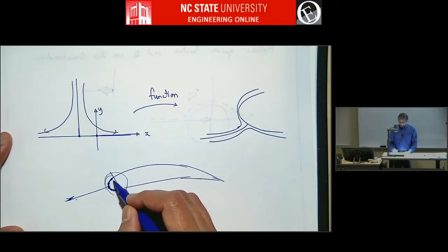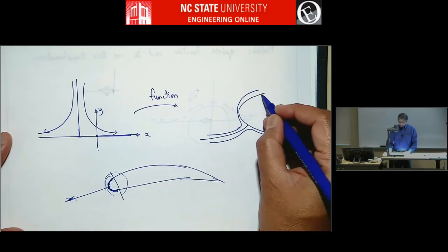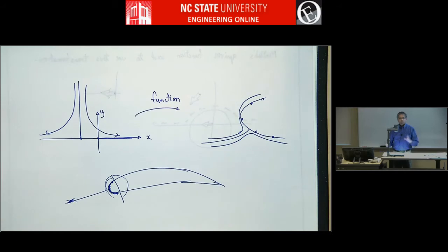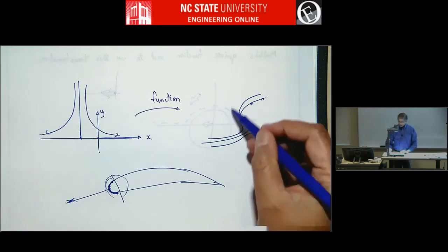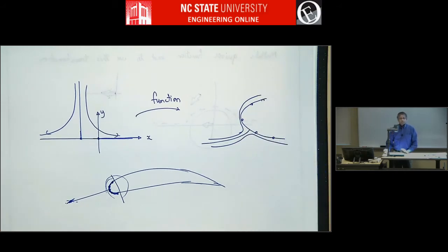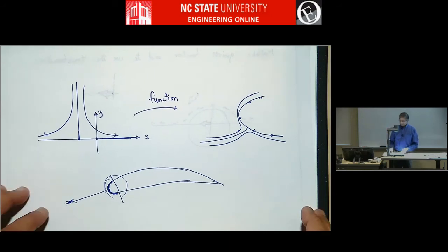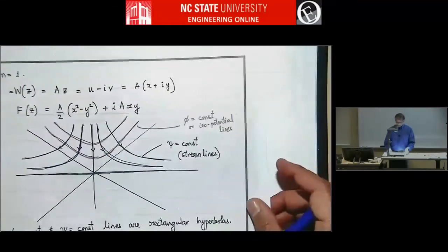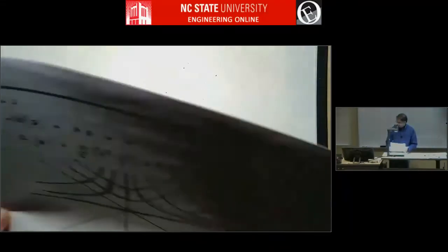So what we came up with was an idea where you can embed 5 pressure transducers or pressure sensors, and by having the analytic flow past the leading edge and with some prior calibration, you can say this is the angle of attack. So anyway, those are the kinds of things you can do by having closed form solutions.